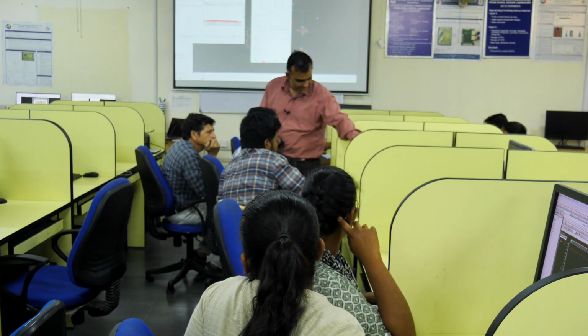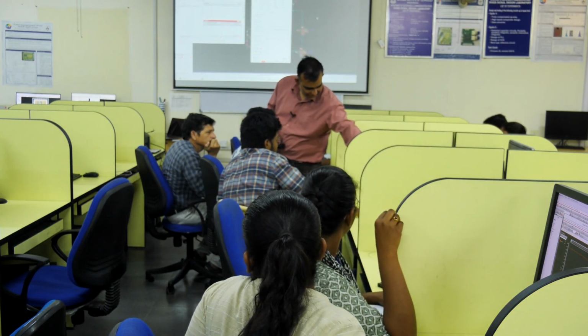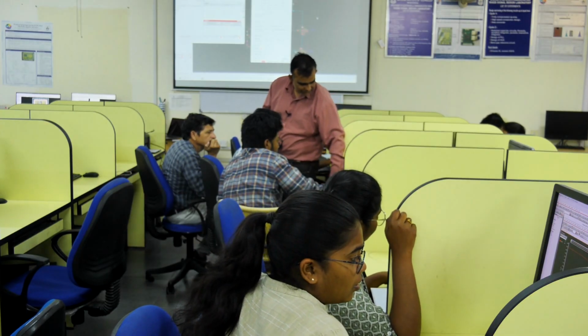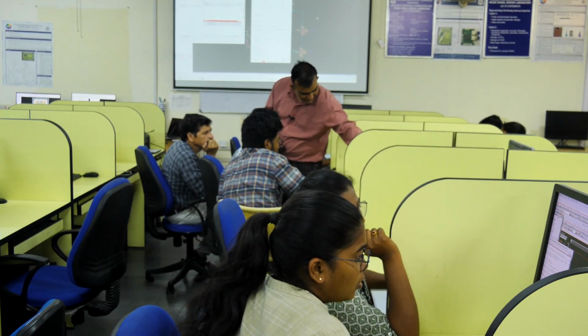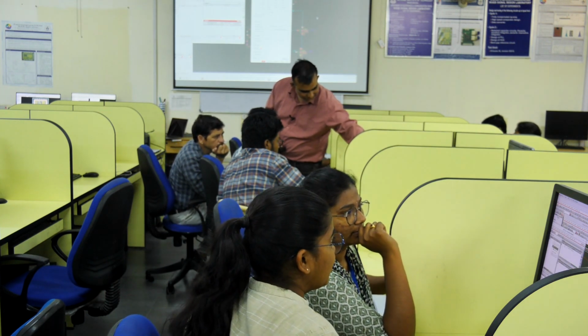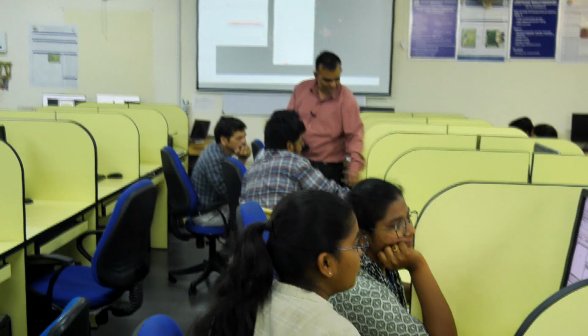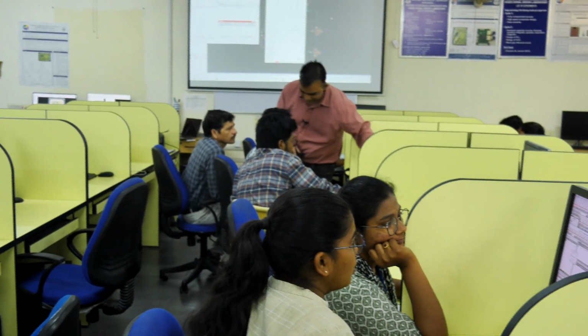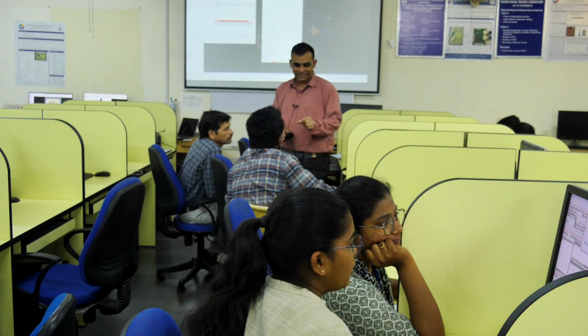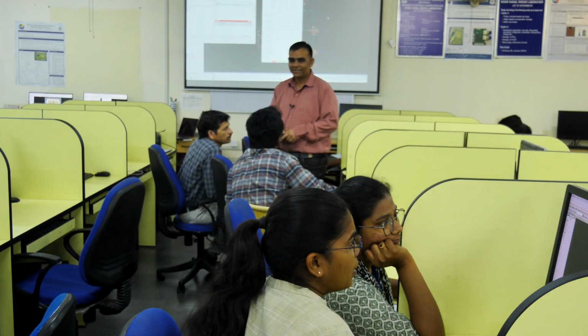This is basically saying you have poly 1 somewhere extending. So zoom in here. You see there is a small gap here. That is saying it cannot make that gap. So we connect it this way and the error gap will go. You have just drawn it here. So these small gaps are smaller than the minimum size transistors which it can make.